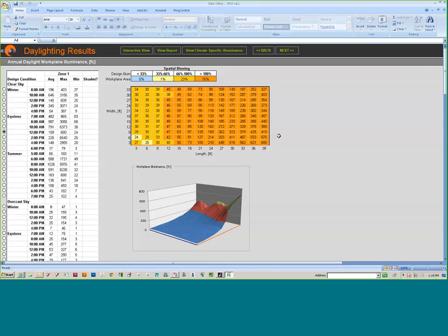you can check that out in SketchUp. Just draw these volumes, space them out as per design, the existing building and your building, and check at these different times of the year if the existing volume in front of the streetscape or something like that blocks the sun hitting your window. You can check that really easily in SketchUp. If that's the case, then you can say the glare is no longer a problem for me. But if, within SketchUp, the sun penetrates even with the existing building, then you have a problem. Okay.